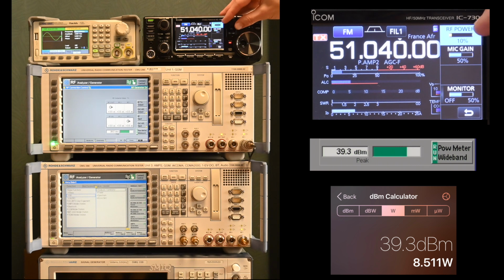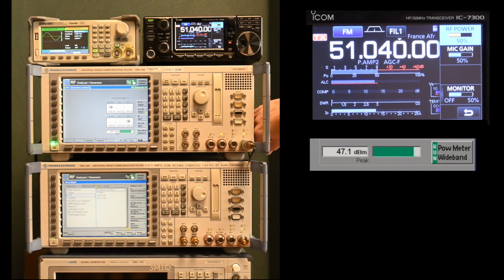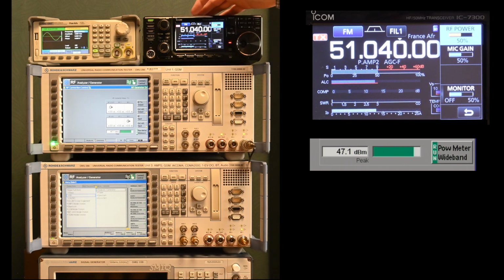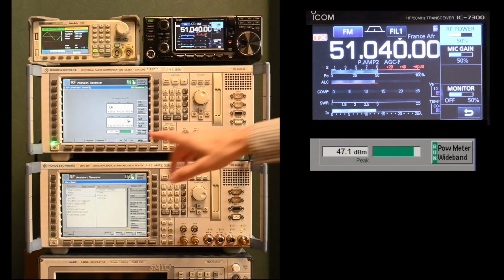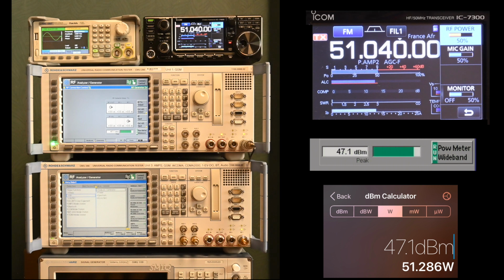And then we should be able to go all the way up without any problems to measuring something close to 50 watts. So let's bring up the output power here. We're transmitting now at 50 watts. All of that is dissipated right now in this unit. It's not getting terribly hot yet. I can also see it from the display here. What we're getting, 47.1 dBm, which is actually equal to 51.3 watts. I checked it in the calculator before. Yeah, so without any trouble we're able to measure 50 watts.